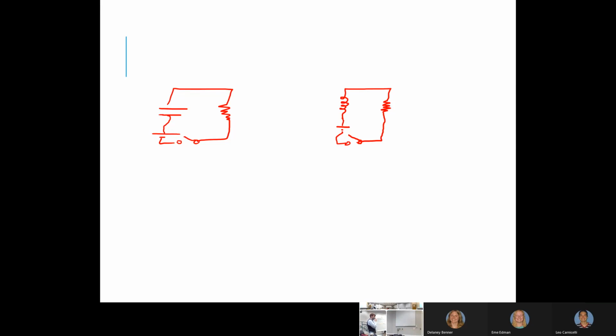A wire. So a capacitor acts like a wire, then starts acting like a break. An inductor is exactly the opposite. It initially acts like a break, and after a long time acts like a wire. So the inductor responds to that rapid current change and then acts like a wire after that. Once this thing is fully charged, once the current stops changing, it just acts like another wire. I mean, it's a wire in a particular geometry, but it's just another wire in terms of circuits.